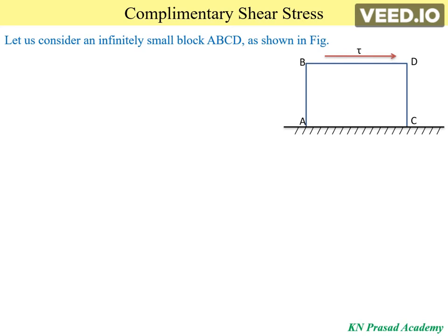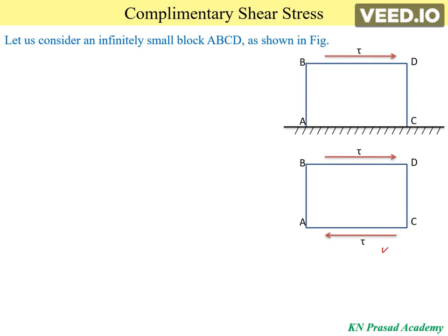Then we have to draw a free body diagram of the block ABCD. And here we have to observe that there is a reaction force, equal in amount to the applied shear stress tau and in the opposite direction, and it acts on the plane AC.